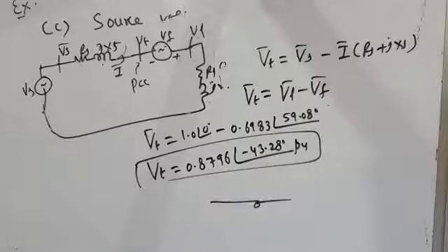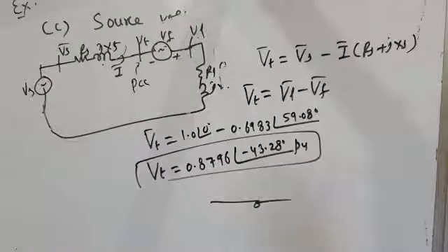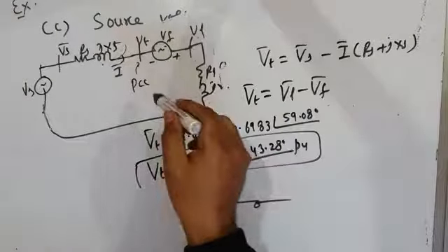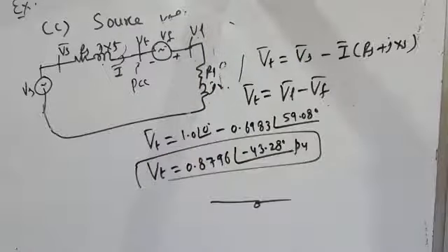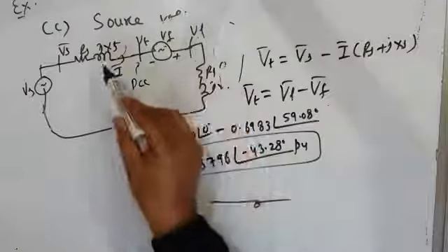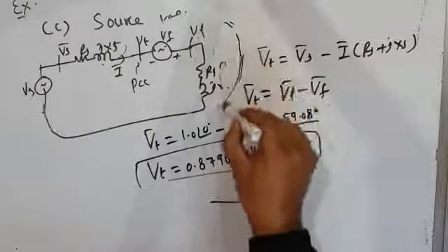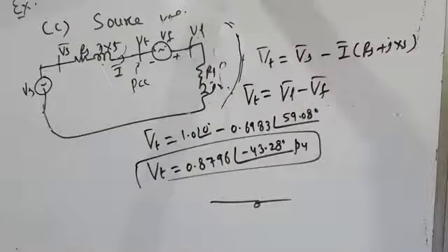In today's lecture, I also discussed with you a generalized phasor diagram, a phasor diagram in the absence of DVR injected voltage and in the presence of DVR injected voltage. And we have seen that in order to make load voltage the same as source voltage, the load voltage should touch the circular trajectory of source voltage. For that purpose, the locus of Vf minus jI Xs should touch this circular trajectory. It may touch it at 2 points or at 1 point.